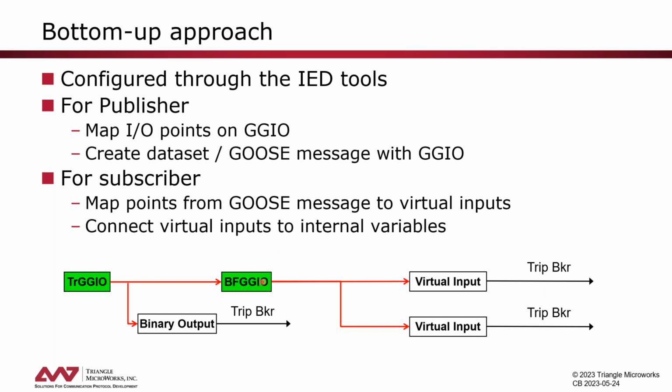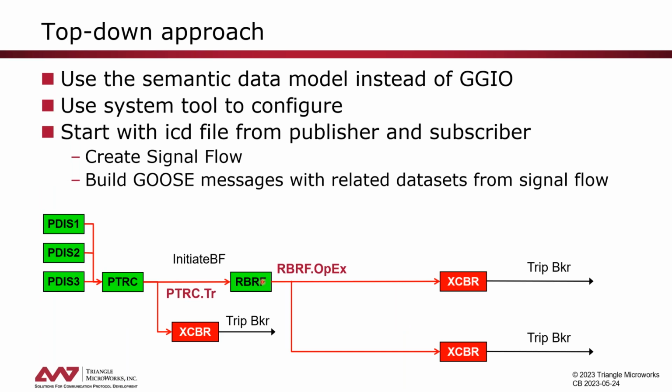So a little bit more enhanced approach could be to do what I would call the top-down approach. So now we are using not just GGIO, but we would really use the semantic data model that we have built into our 61850 devices and use the system engineering tool to configure. So use basically the IEC 61850 engineering process as we have introduced it in part 2 of this webinar series.